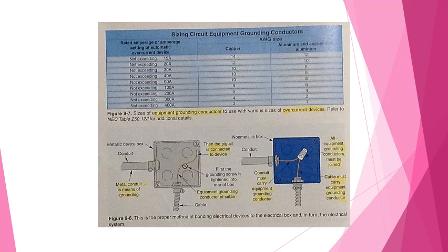At all service equipment enclosures, whether inside or outside of the building, and all metallic components of the electrical system that normally carry no current. If a grounding electrode conductor is properly bonded to the metal service equipment, a fault between an ungrounded conductor and any grounded equipment will follow a low resistance path to the grounding conductor at the transformer. This would allow the OCPD to open the circuit rapidly.